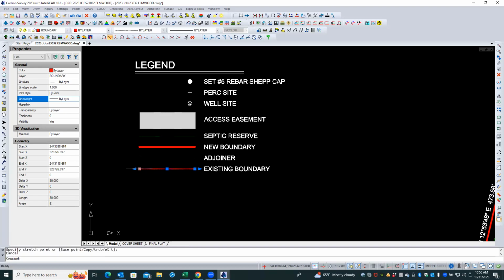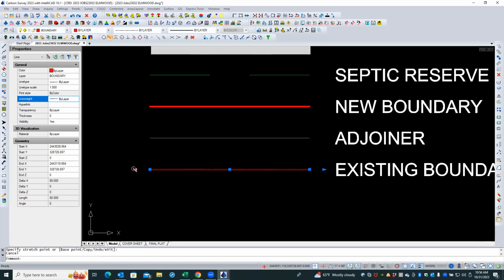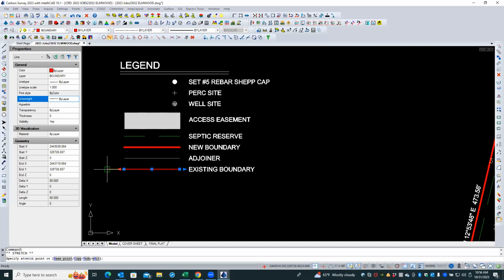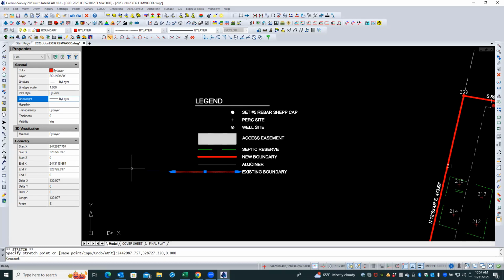Here's a little trick. Because it's a line and not a polyline, if you grab the arrowhead, it's going to extend the line and not change its direction. So you don't have to worry about locking it to be orthogonal. So now just drag it to the left. And I would zoom out a little bit so you can see more of the screen, and now keep going to the left. Keep going right in there maybe, because you want to get it over here.